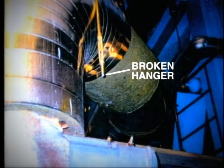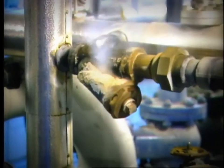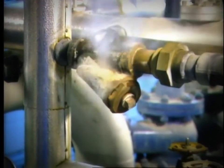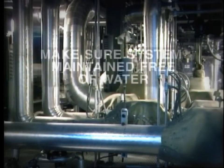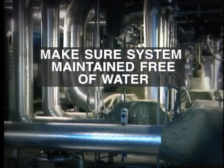The water hammer can produce considerable mechanical movement and shock to the steam pipework and may result in broken hangers and supports, as well as leaks at valves and other equipment connections. In operating any of the steam systems, one of the most important operating requirements is to make sure that the system is maintained free of water.